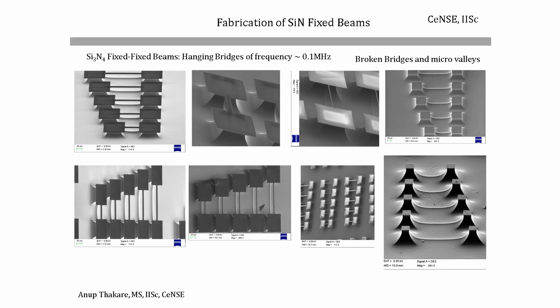So before and after, what dimensions we desired, what dimensions we started off with, whether we are able to get the same or the desired dimensions back, for which we need to do optical profilometry, step size detection, as well as feature size detection from optical micrographs, microscope, and then finally an electron microscope image to see the structures that we have made.